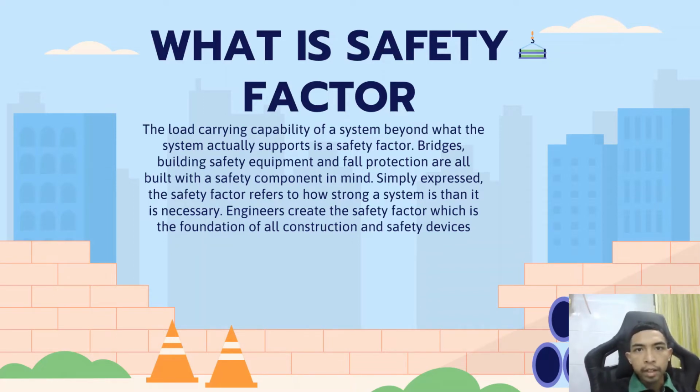How do we analyze the force and safety factor of actual structures? First, we create an idealized model of the structure. Second, we state the structure assumptions. Next, we create an FBD. Number 4, we create the equations of equilibrium. Then we analyze the forces operating on the structure, and last but not least, we determine the system's maximum permitted forces and the safety factor from the actual diagram.